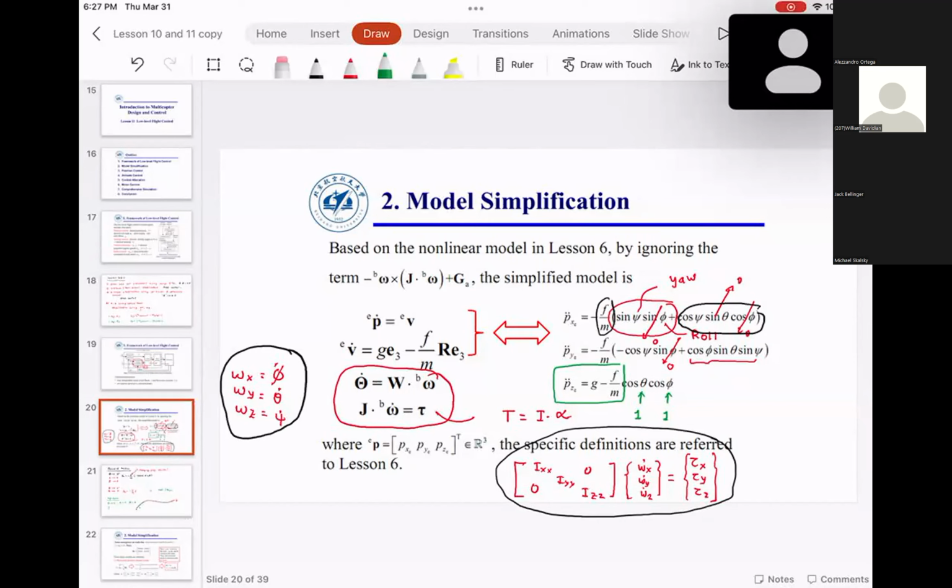Essentially, your thrust is always going to be upward. You will never have thrust going downwards. In this particular case, the equation is written with G positive because the coordinate system is different. In our north-east-down coordinate system, our G is going down and our F is going up. Other than that, the implementation is the way I discussed.